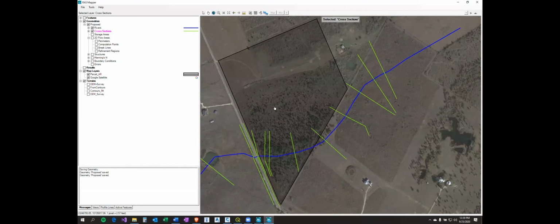Have you worked with the floodplain analysis in AutoCAD? I have, and honestly, it is a pain in the butt if it works. Yeah, I've been dealing with the Brushy Creek stuff, and it crashes if I try and reopen the file. Yeah, every time I make something in it, I essentially have to start over because I make a model, save it, close it, reopen it, and it won't open. Yeah, it crashes immediately. And it's also not approved by most cities for their floodplain modeling, right? It is HEC-RAS, it's the same engine. I don't know, but I can't get it to work nearly as efficiently as HEC-RAS.